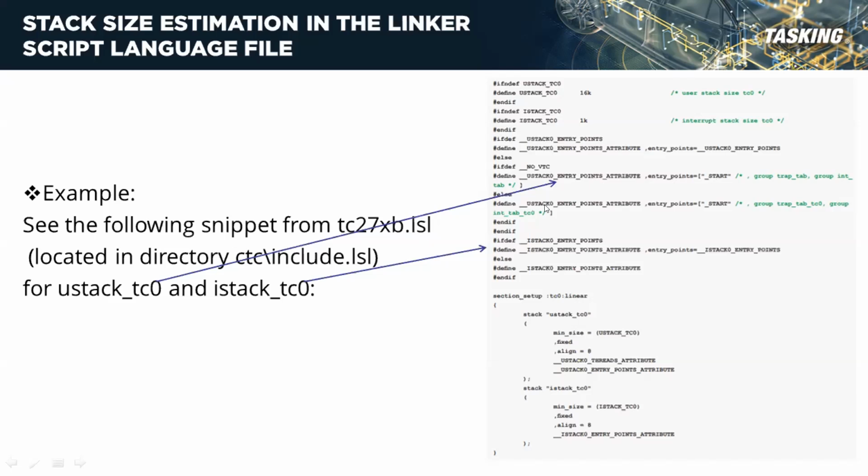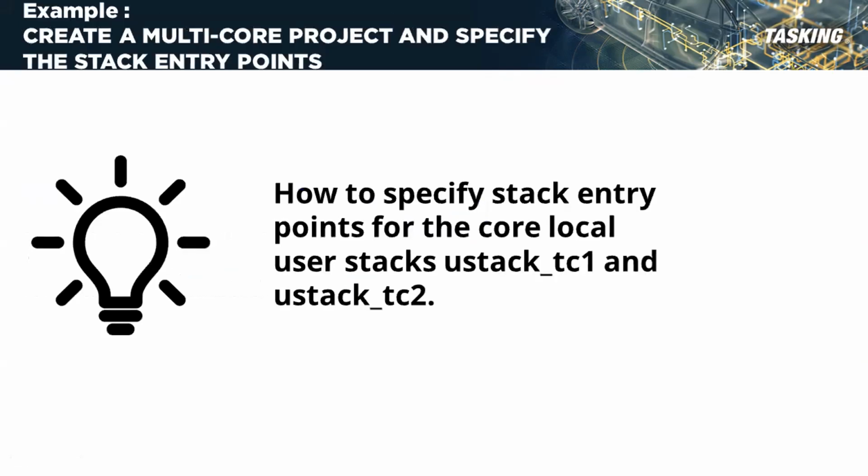And again, this will be for the interrupt stack. So this is for the user stack, and this is here for the interrupt stack. I will give you a very simple example of how you could use this feature, the LSL macros, in order to measure the user stack for core number 1 and for core number 2.